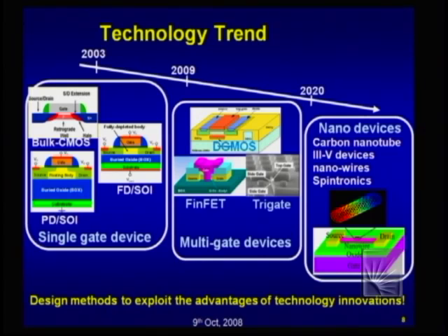So, people have thought about replacing one gate structure by multiple gates. So, they have talked about 2 gates, they have talked about 3 gates. For example, Intel is promoting a tri-gate structure where each transistor will have 3 gates, which is wrapped around the channel. AMD and IBM are looking into a structure called FinFET, which has multiple gates. Again, the motivation is to have better control on the channel conductance. So, that effectively gives you less leakage current and better performance. So, these are called multi-gate devices.